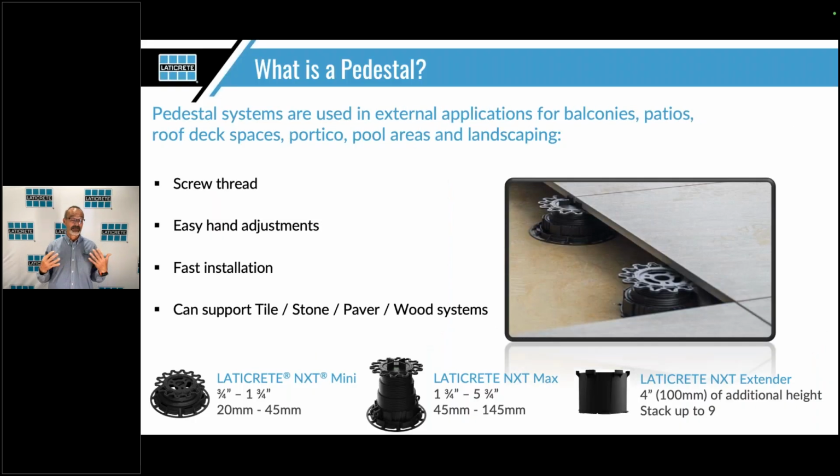Now, most of the pavers out there on the market are screw thread. I will say the nice thing about ours is it's an easy hand adjustment. You can just basically spin them into position, so you've got a really, really fast setup when you're working with these. We have systems that will carry tile, stone, paver, wood systems. Basically, if it's designed to be a finished floor and it meets the characteristics of a pedestal system, we have a way of adapting to that.